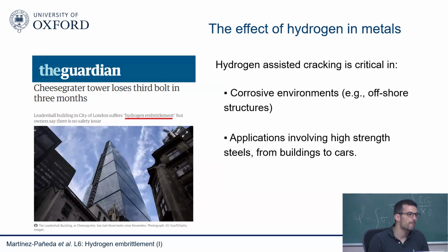So this effect of hydrogen, is it limited to steel alone or any metals? All metals will, there are different effects. For example, if you're looking at titanium or zirconium alloys, you'll form hydrides, so it's a different type of phenomenon. The susceptibility of metals can change quite dramatically. Some are very susceptible, others less, but they're all susceptible to hydrogen embrittlement.